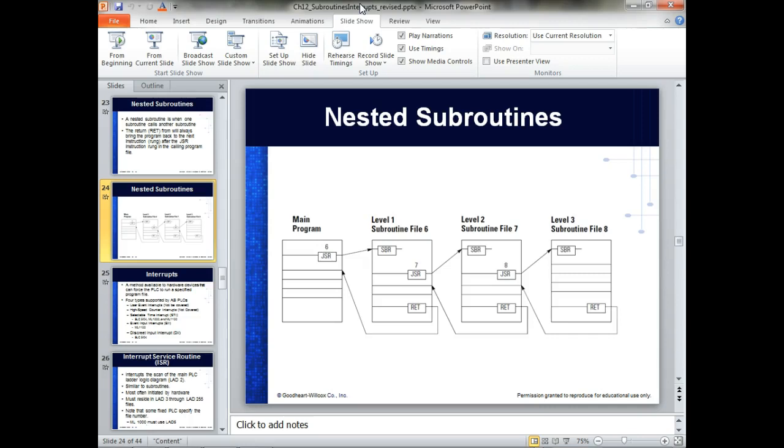Nobody needed service, but that's the way the processors originally ran. It would come up here and scan all the inputs, right? You understand? So I've got all these inputs on there and it's going to scan all those inputs. It's going to run the logic and update the output. There's got to be a better way to do it. Right? What would be a better way to do it?